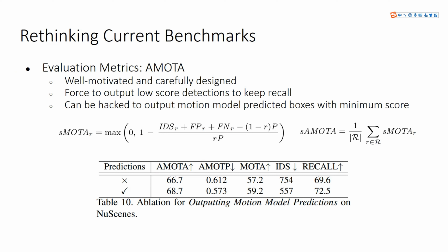Yeah, the key here is that just like in detection, we all use mAP for evaluation in academia, but actually we don't use mAP in on-board testing. Why? We use metrics such as FPPI for the evaluation of detections, because we need to set a threshold for detections to downstream applications. So that's the difference here.